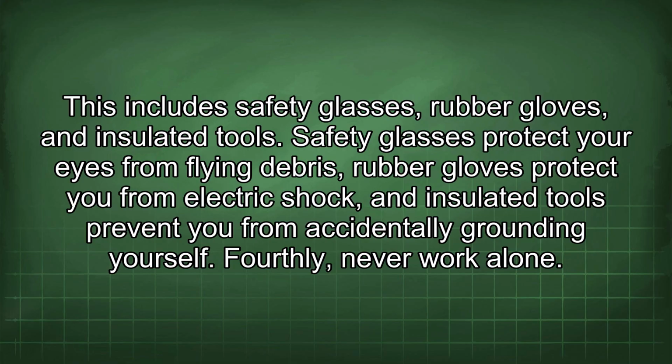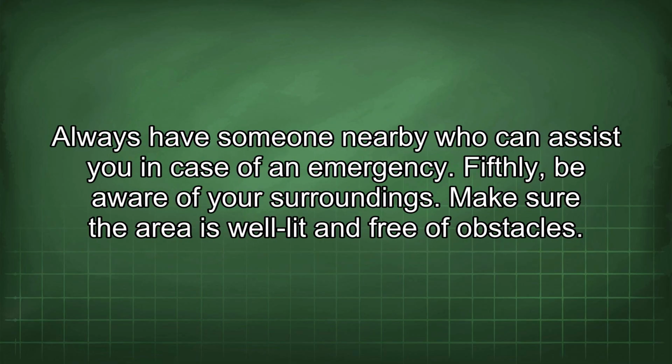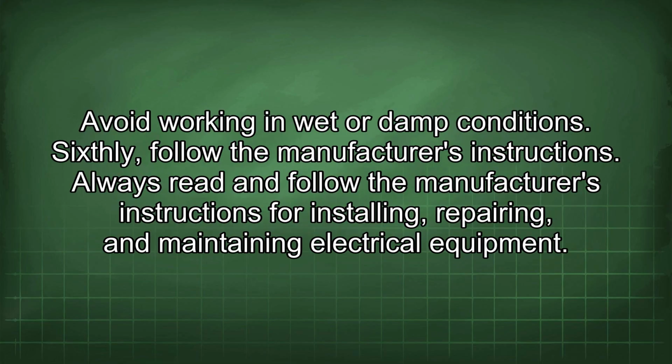Safety glasses protect your eyes from flying debris, rubber gloves protect you from electric shock, and insulated tools prevent you from accidentally grounding yourself. Fourthly, never work alone. Always have someone nearby who can assist you in case of an emergency. Fifthly, be aware of your surroundings. Make sure the area is well lit and free of obstacles. Avoid working in wet or damp conditions.